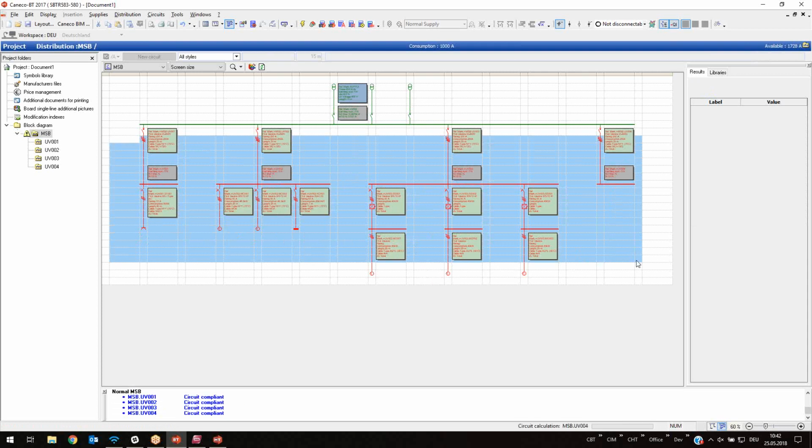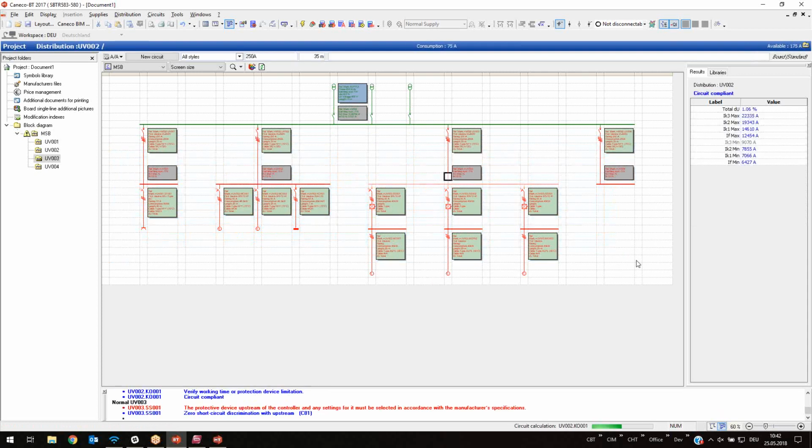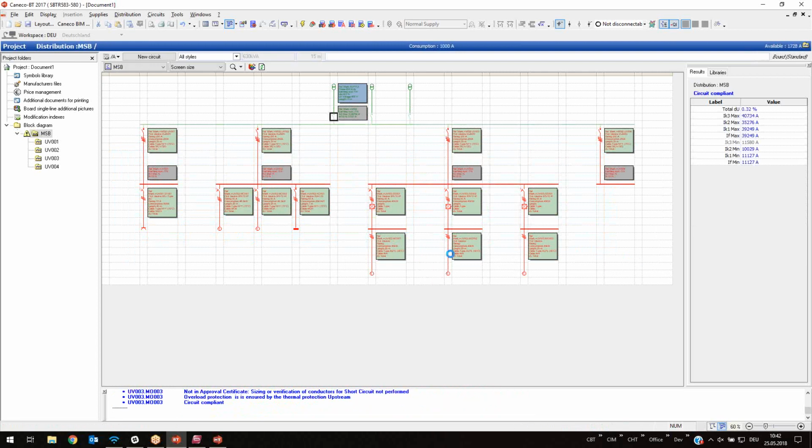Because of the drive in between, or? No, because they were not calculated before, and here we had a factor. We say not both are in use; it's only one each time. So also for this value we added here, there was only one motor considered. Because if one motor is rotating and the other one not, I cannot take the short circuit current of both, of course, for the calculation.